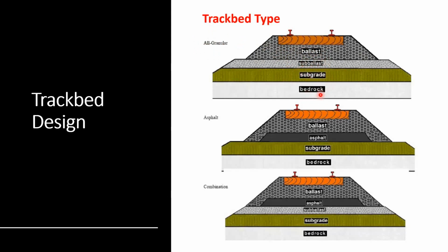Now bedrock is not a necessity here. Sometimes it's a stiff soil compared to the overlying soil, or sometimes just the natural damping that would happen when the surcharge transfers the load with depth. So don't think of it as a bedrock geologically, but more like a refusal surface, or a surface where the effective stress does not increase significantly due to the overlying load from the ballast, sub-ballast.